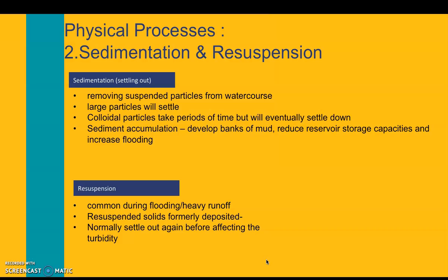The second physical process is sedimentation and resuspension. What is sedimentation? It is removing suspended particles from the watercourse. Normally, it is for suspended solids, so it will involve large particle sizes. Large particles will settle down, and colloidal particles also will take some time to settle down.